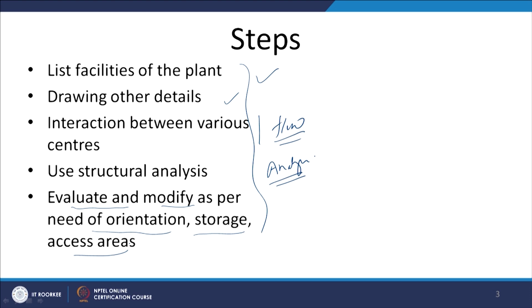We have seen the analysis of the information about the kind of flow which exists across the centers. There are three approaches used in process layout design. One was the proximity analysis, about which we have already talked. This is based on the affinity or closeness desired between two work centers, so that they can be placed close to each other or apart from each other. So, it is a qualitative assessment of putting the facilities close to each other.